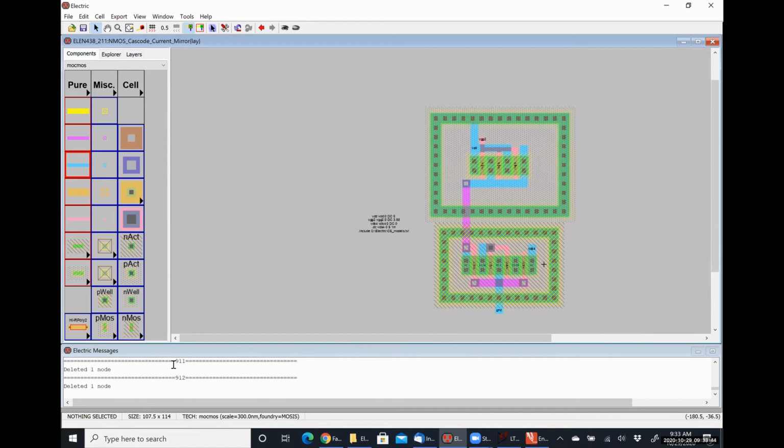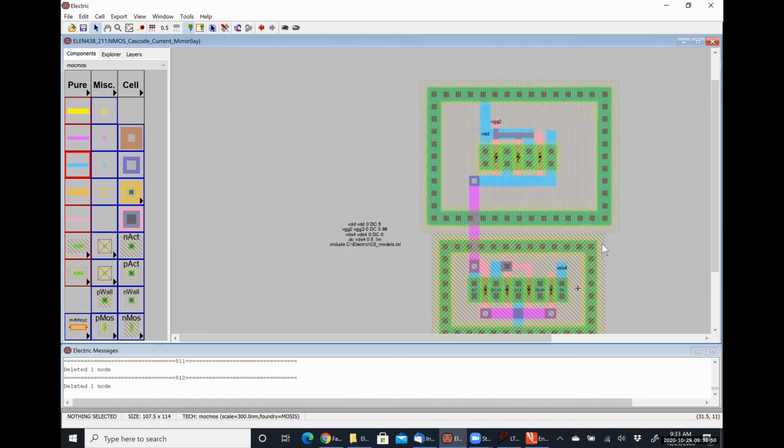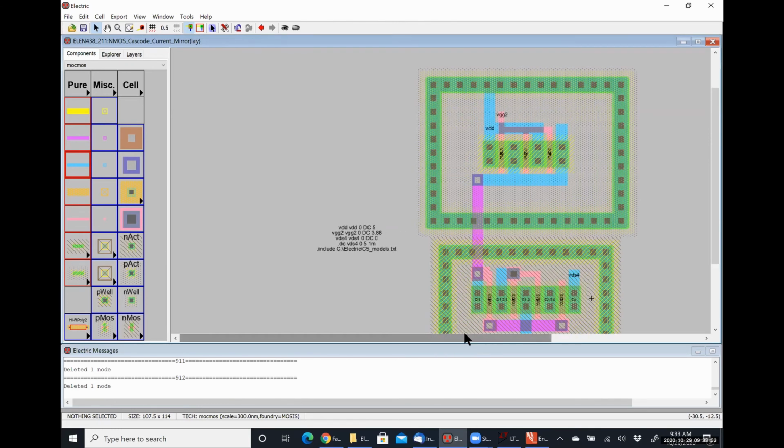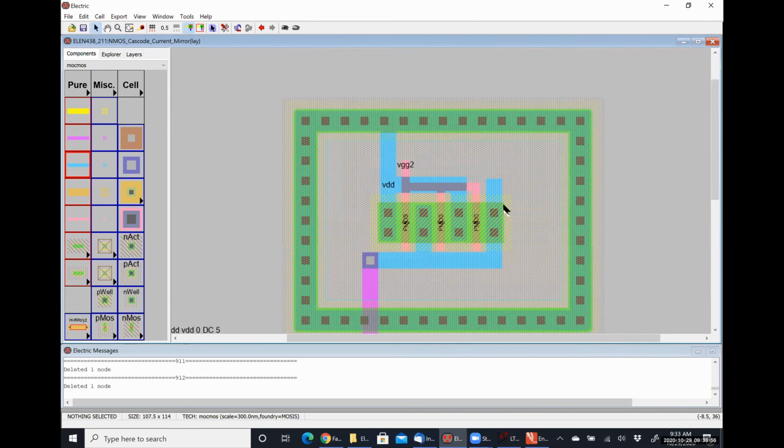So for the top gate, in that setup, you have it all on the top of the transistors. Would it be better to connect it across the bottom between the first and second transistor, so it's only crossing at that one spot and then across the top? So you're saying effectively make a serpentine type thing. Yeah, so I kind of mirror what the metal runs are doing. Would that be less capacitive, I guess?